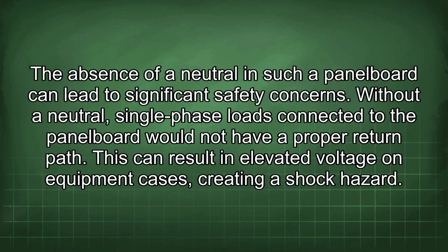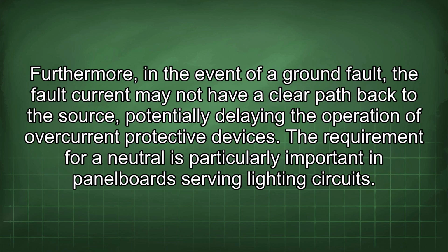The absence of a neutral in such a panel board can lead to significant safety concerns. Without a neutral, single-phase loads connected to the panel board would not have a proper return path. This can result in elevated voltage on equipment cases, creating a shock hazard. Furthermore, in the event of a ground fault, the fault current may not have a clear path back to the source, potentially delaying the operation of overcurrent protective devices.